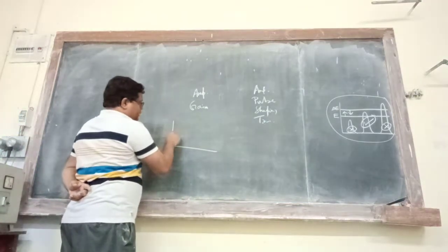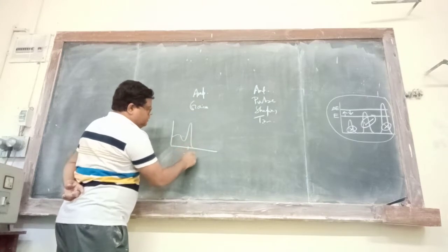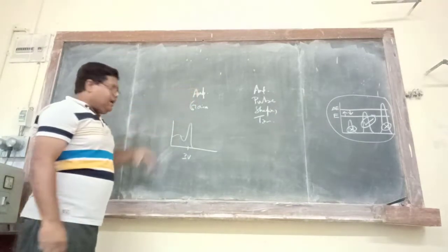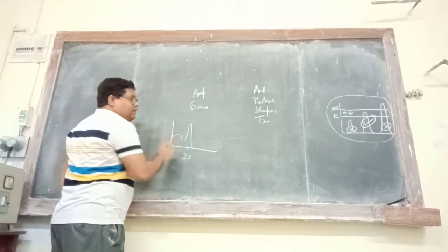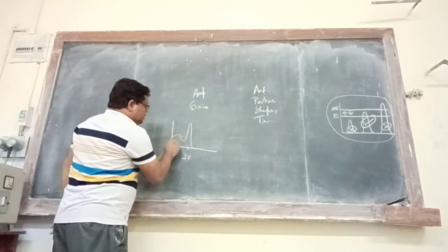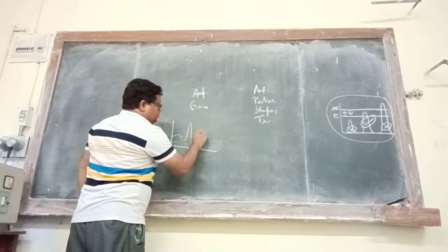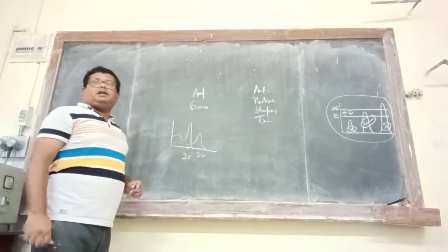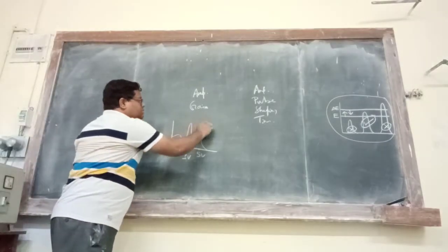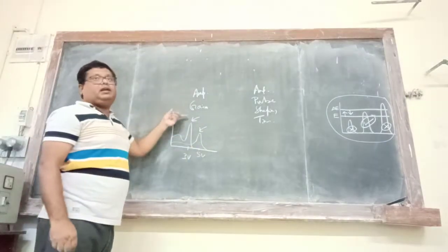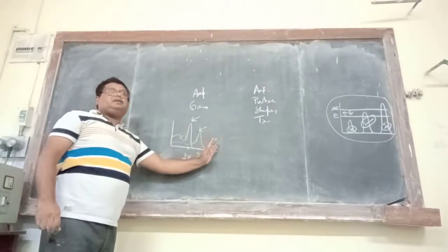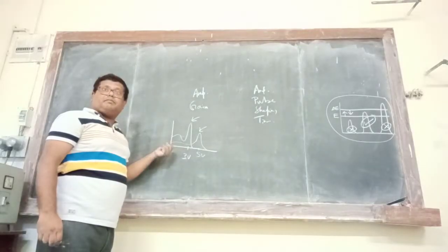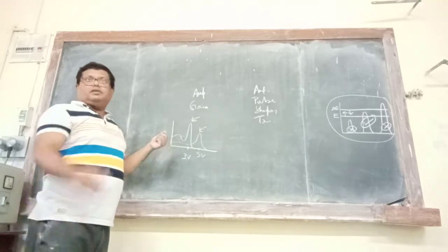Suppose this spectrum was observed as 3 volts. Now I can change the gain of the amplifier, and if you do the measurement for 30 seconds again, here it is 3 volts. See, the overall area will be conserved, will be equal, but the peak changes, and this is the result of the gain in the amplifier. You change the gain, the entire spectrum changes, but the overall area will remain fixed since the timing for the 2 measurements is the same. You can check this over here in this module.